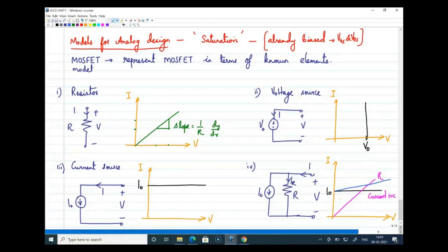Okay, so you are asking me, now you have a current source in parallel to a resistance, and you are applying some transformation to convert that current source in parallel to a resistance into a voltage source in series with a resistance, isn't it? Yes, sir. Okay, so when you do that, your response will not look like this, because you have a voltage source and there is a series resistance. Your response will be quite different from this.